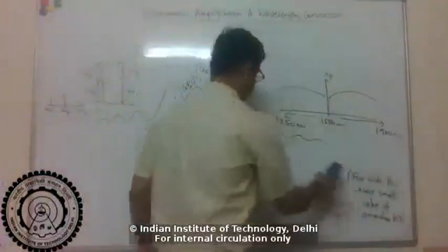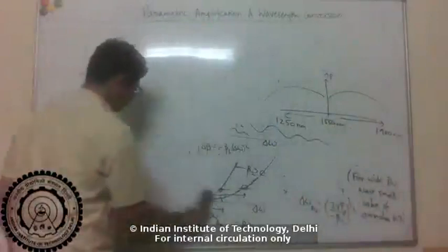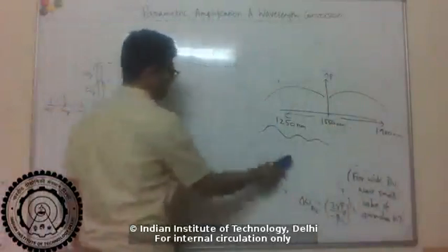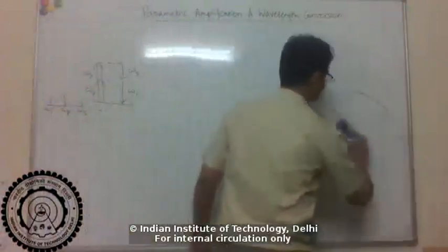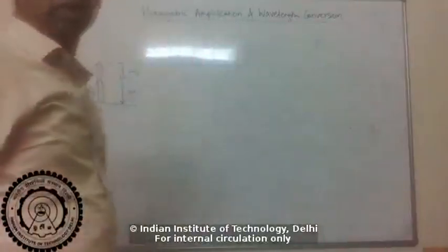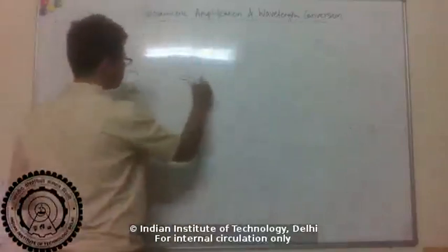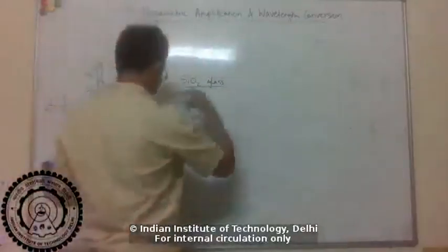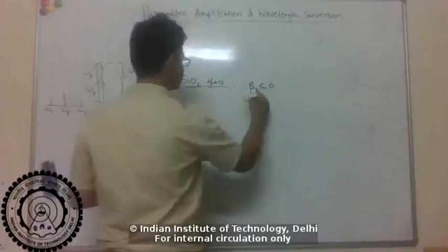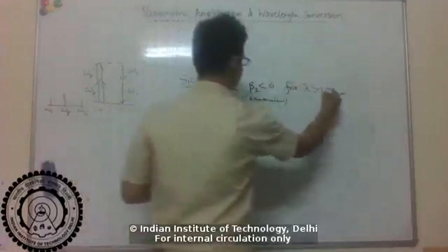Okay, so as I said, you want anomalous GVD, which is actually not the norm, right? Typically what you will have is normal GVD. So like many discoveries, there are some quirks of nature which help you at certain points. This whole optical telecom revolution happened with a lot of accidents that nature gave us. One of them, for example: if you take silica glass, which is what we use to make optical fibers, it turns out the material has anomalous dispersion for wavelengths longer than 1.3 micron.